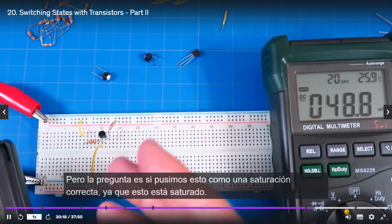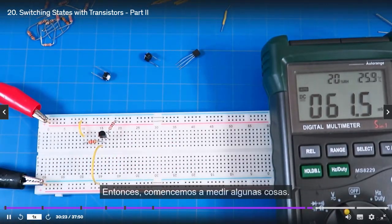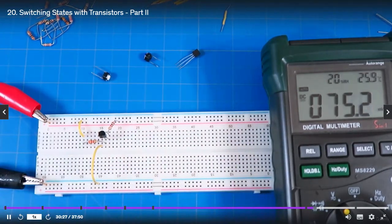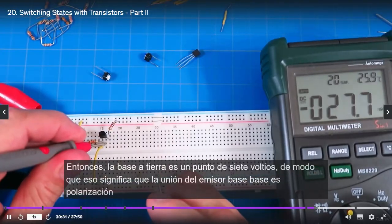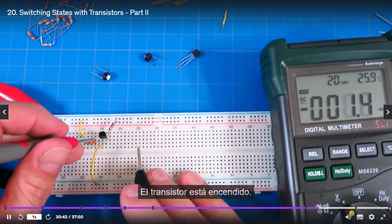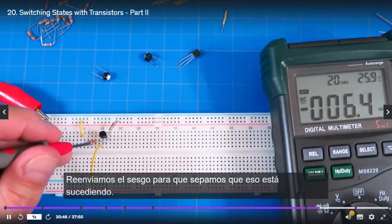But the question is, did we put this into, say, saturation, right? Is this thing saturated? So let's start measuring some things. Okay, so let's measure what the base is. So the base voltage, the base is right here. So the base to ground is 0.7 volts. So that means that the base emitter junction is forward biased. So this transistor is on, so it's forward biased.